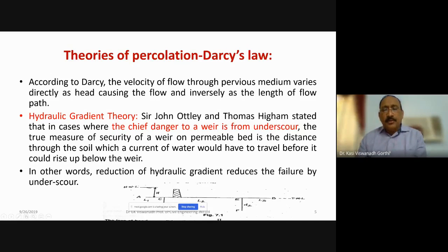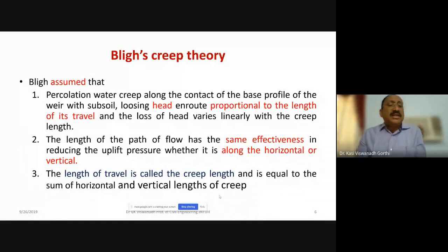A simple line diagram for a weir is shown here. This line diagram provides you a weir wall which is resting on a foundation. The length of the foundation is given to be ACEB, the total length of the foundation. And for this you have cutoffs, sheet piles which are provided at C, which is called the upstream pile, and another, EF, a downstream pile. Then H, of course, is up to the water level, up to the crest level.